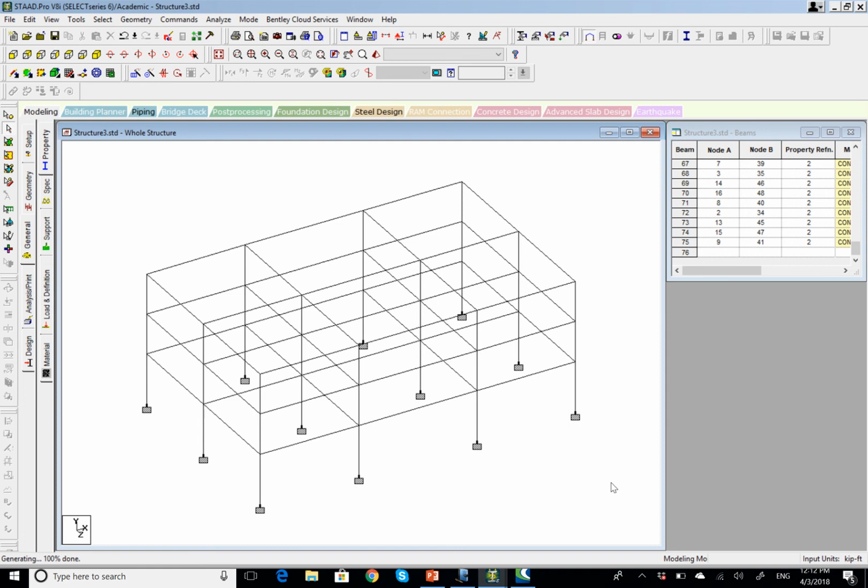You did the calculations for the dead load, for the live load, for the wind load, for each and every member. Just define the dead load and the live load. And for the live load, just do as we did over here. Define the live load on those parts, and then those parts. And then you're going to have 4 different load combinations for the live load.